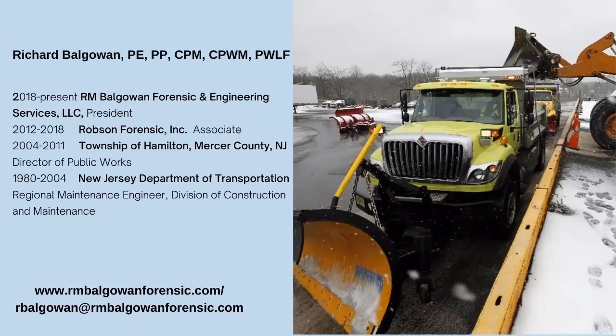This has been studied to death. There are best practices out there, published best practices on how to properly apply anti and de-icing chemicals to the roadway. And when I talk about anti-icing, the whole purpose of salting a roadway is to prevent the snow and ice from bonding to the pavement. You want to keep snow and ice from bonding to the pavement so it can easily be pushed off. In some cases, it could be broomed off if we're talking sidewalks and things like that, or just put the plow down and push it off.